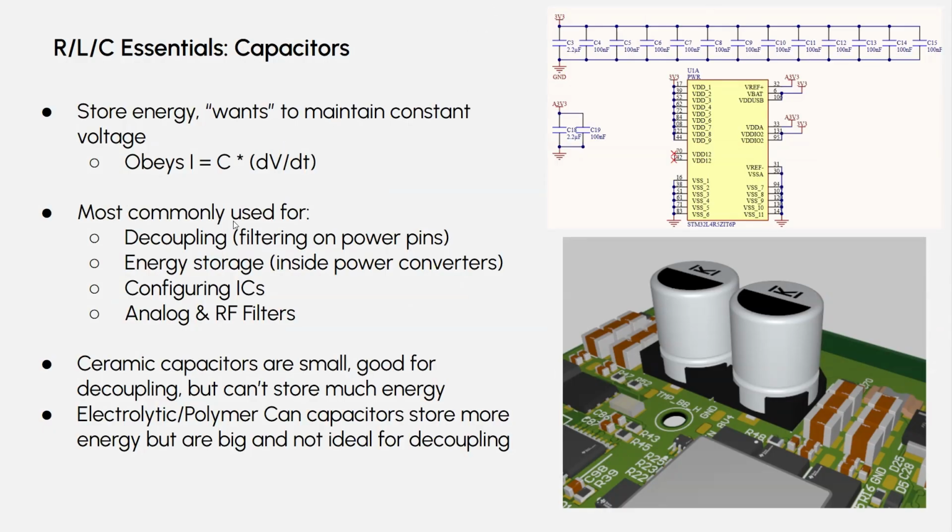So the key use for capacitors really is for decoupling, which is something we'll cover, and just general energy storage in power converters, which we'll cover later as well, buck and boost converters. And also configuring ICs. Sometimes they require a capacitor to set some sort of mode. And analog and radio frequency filters, which we're not going to cover today, but they are used in that.